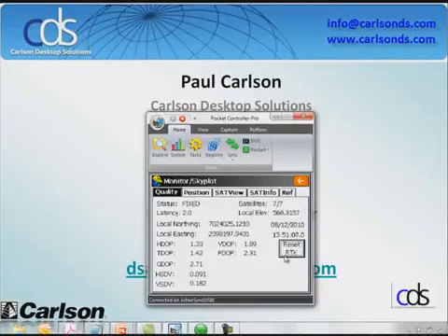The other important thing to bring up is the Reset RTK button. Years and years ago, the first time I picked up a GPS receiver, we went out on a site and started surveying. We got in a bad area and couldn't fix, so we floated, we waited a while, and it never came out of float. So the first thing you did is you turned the receiver upside down. You dunked the receiver to let it clear out that position and start over, essentially. What really happened is the position didn't completely clear out. There was bad information, or could potentially be bad information left over in that position, multipath and other things.